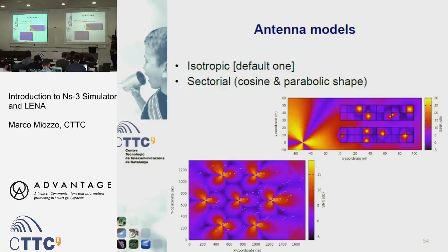These, for instance, are an example of a building solution. This is a typical 3GPP scenario called the dual stripe scenario, since we have two stripes of apartments, rooms. This is usually evaluated for testing interference coordination when we have small cells coexisting with macro cells. And this is a typical outdoor scenario with a hexagonal deployment of the antennas, like the one we typically have in deployments.